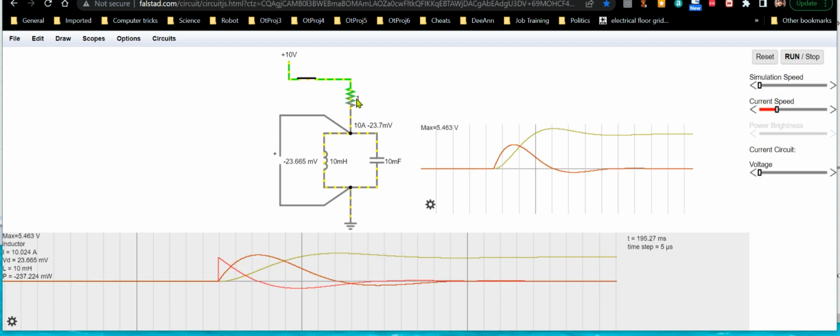Now, if I used a bigger resistor value here, you would actually see a lot more oscillations in this. If I put a 10 ohm resistor in there, which is what I originally started with, it takes like 4 or 5 seconds for this to stabilize at 0 volts. So even right here, it's not exactly at 0 volts. It's still oscillating a little bit, but it dampens really quick. So that's why I use the values I use, just to give quick results so we don't get too confused, and you can see everything on the same screen. But at any rate, this basically is the stable state of the circuit.